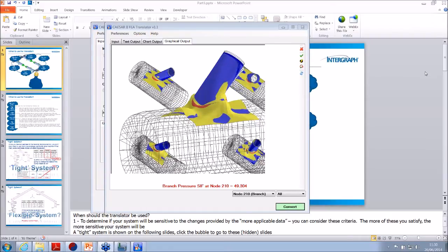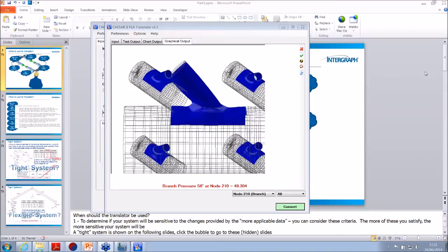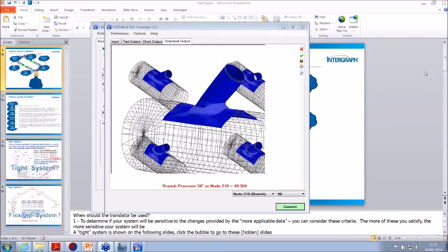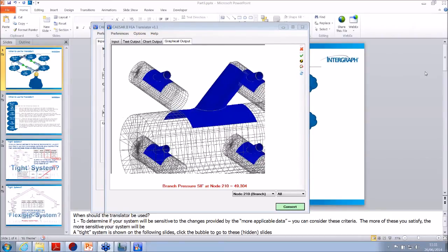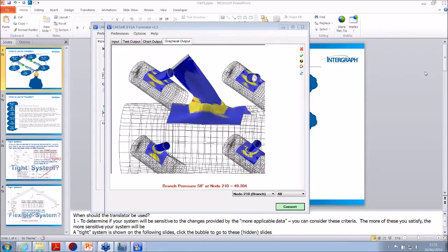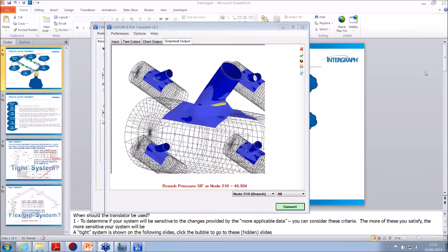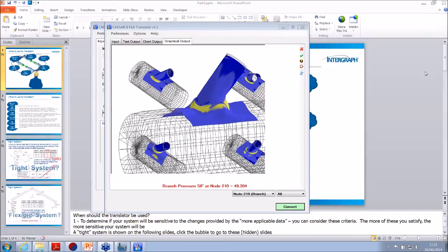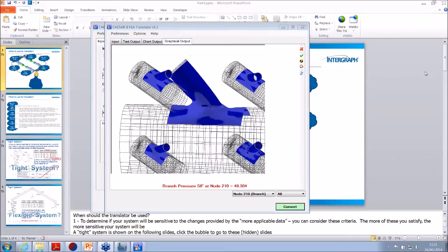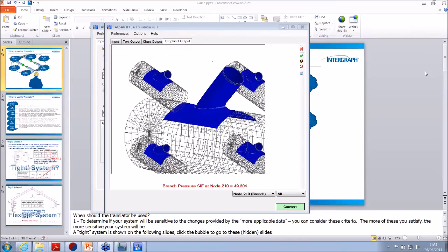Okay, thank you. And is the FEA calculation carried out for the whole pipe system, or individually for every T section? Yes, individually for every intersection. Then the results of the FEA, the flexibilities and the intensification factors, are passed back to CAESAR II in the form of a new model with those incorporated at the appropriate locations, which we'll take a look at in a minute.